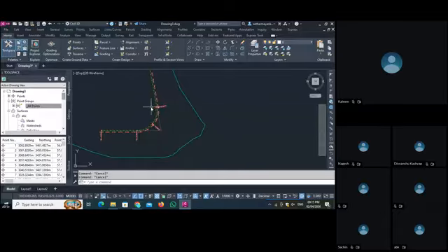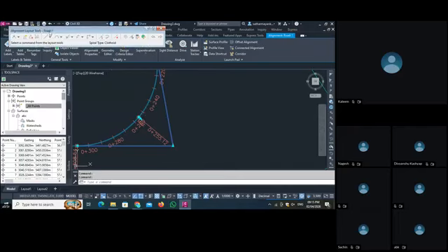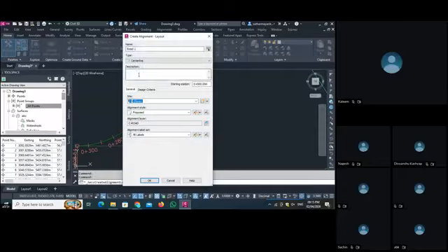I close this. So once you create, you can close that pop-up bar. Now if you want to reopen that pop-up bar, you select the alignment and you select here the geometry editor. As you select it, the same thing comes again. Now we go again to create alignment.